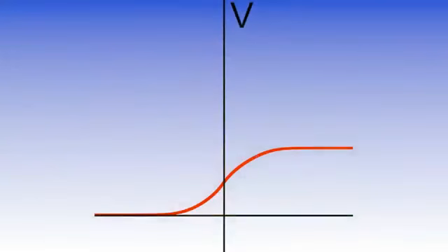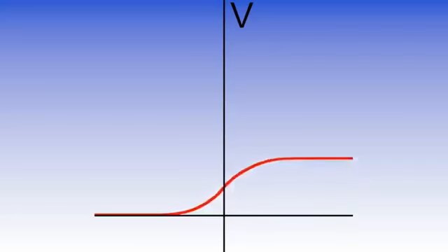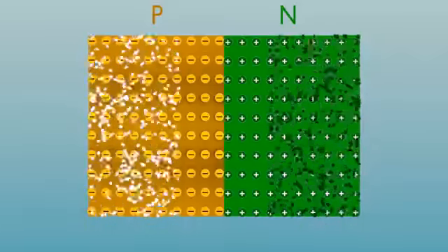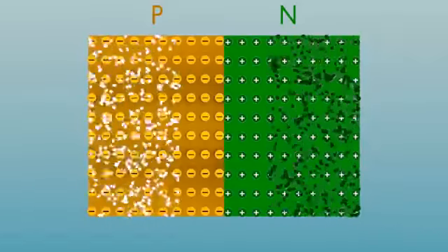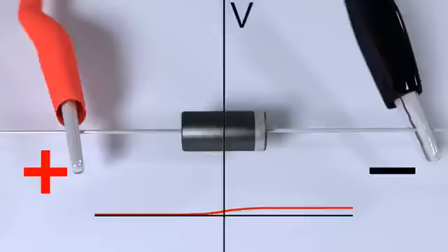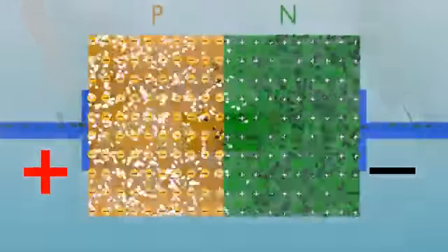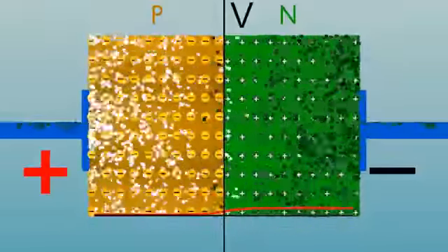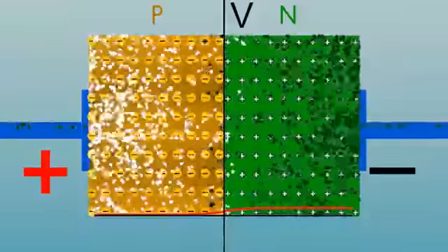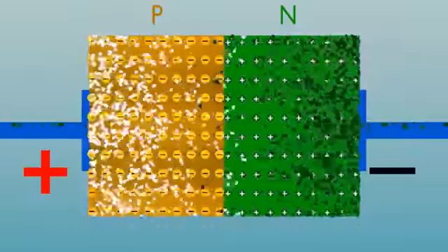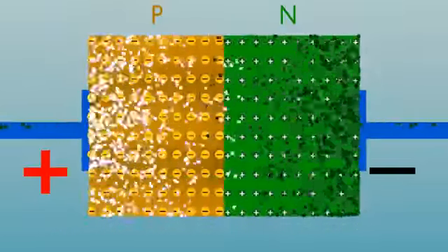The potential barrier is an obstacle for the diffusion current in the device. It is possible to reduce the height of this potential barrier by the application of an external voltage. This increases the electric current. By applying an external voltage from a battery, the height of the potential barrier in the junction is modified. If a positive voltage drop is applied between the p and n regions, the barrier height is reduced. A reduced barrier cannot prevent electrons and holes from diffusing across the structure. An electric current appears in the junction due to the diffusion mechanism. Under these conditions, the p-n junction is said to operate under a forward bias.